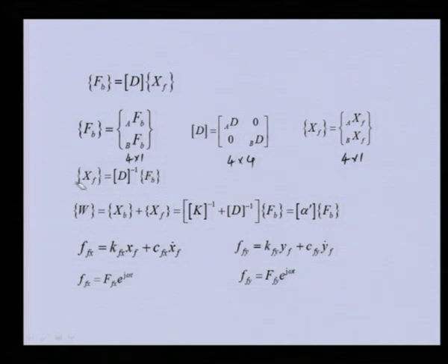Now, this particular displacement is of the pedestal. Earlier we obtained the bearing displacement, so we can add that bearing displacement to this pedestal displacement. So, we will get the total displacement, not only because of the pedestal but also due to the bearing. Earlier we related this as K inverse Fb, and here we have related xf as D inverse Fb. So, we can substitute that.